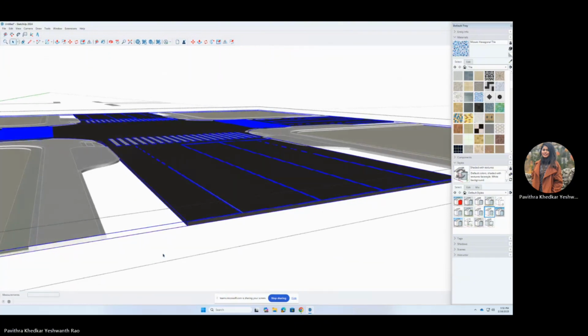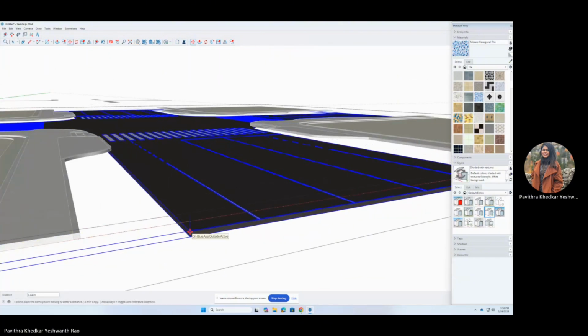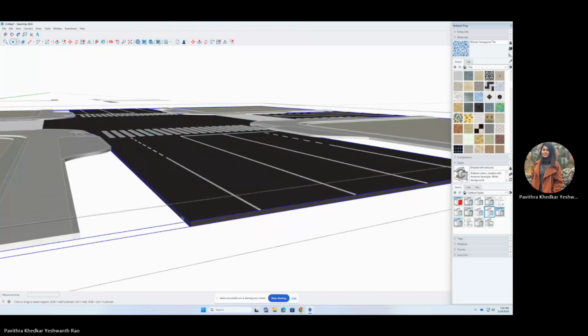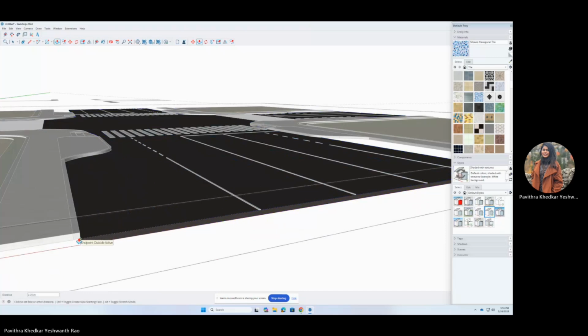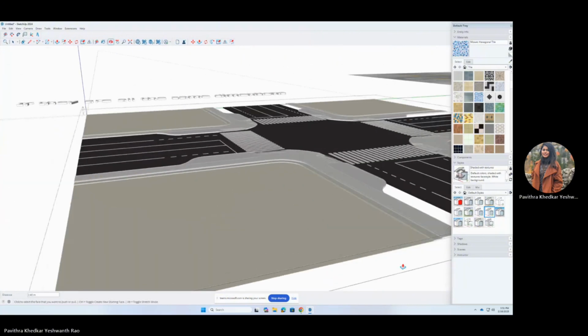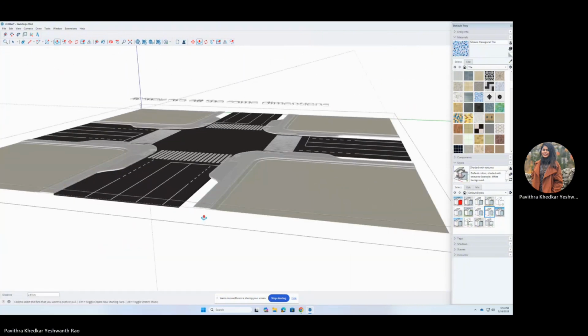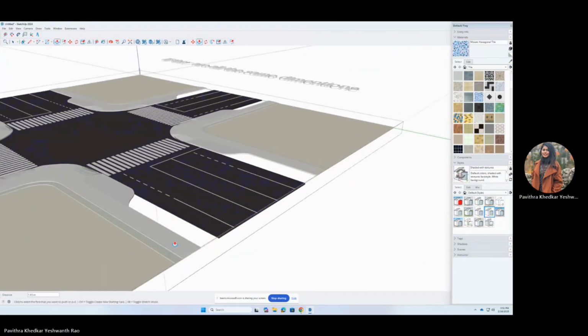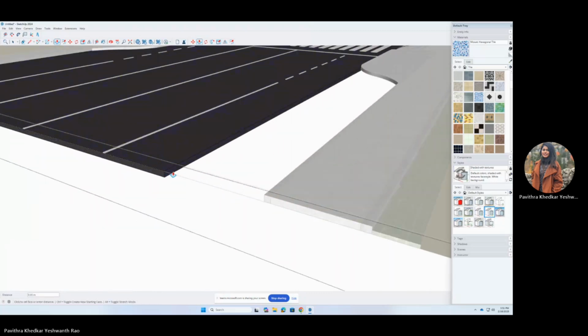Handling hidden geometry in groups and components could be slightly different. If certain elements remain hidden and they may be within a nested group or component, go back to your View tab and select Show Hidden Geometry to make all the hidden lines visible.